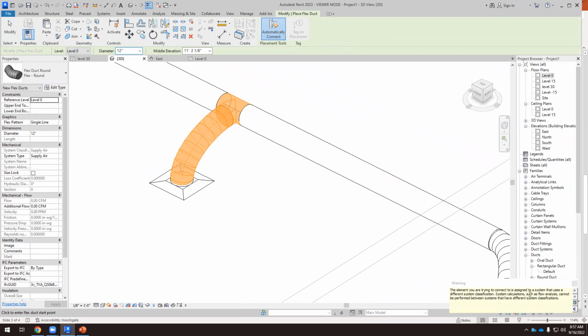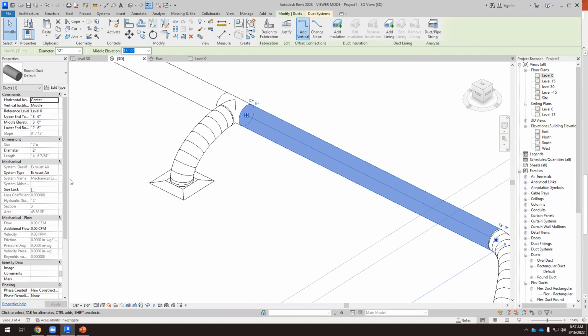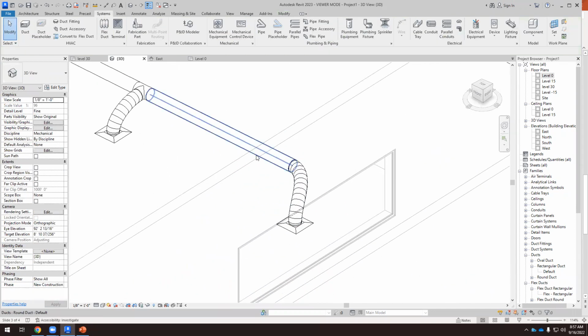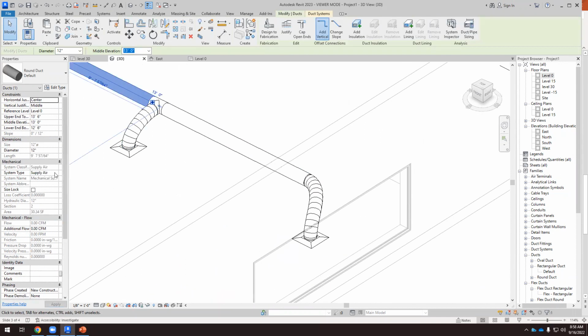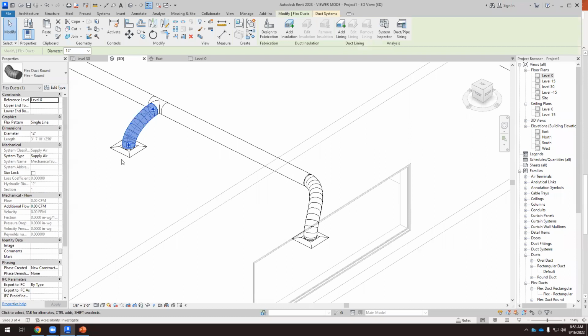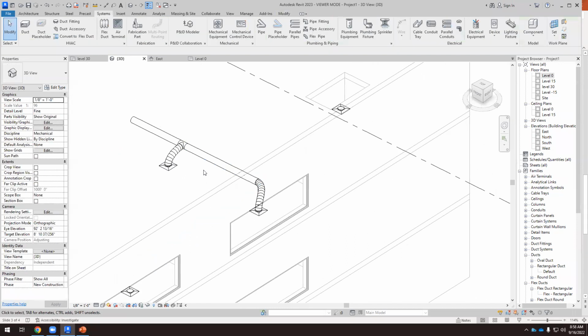and the element you're going to do the different system classification. Okay, so that's interesting. What's wrong? I don't know if this happens to you, but to me, this is an exhaust air duct. Okay, so check, because we have this warning, it couldn't happen, it has to be supplied. And this has to be supplied. And this is supply, and now everything is supplied. I don't know why it has happened. But now we have to check the flags.